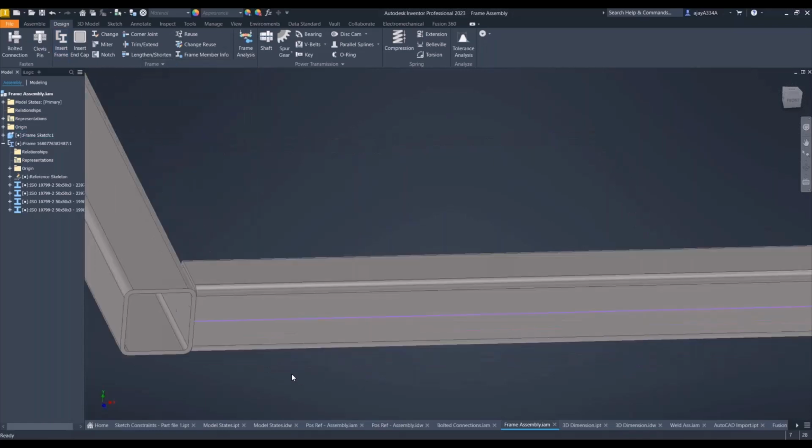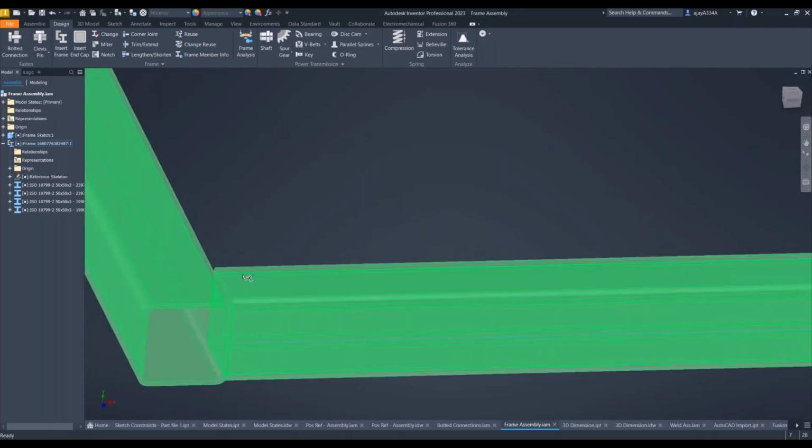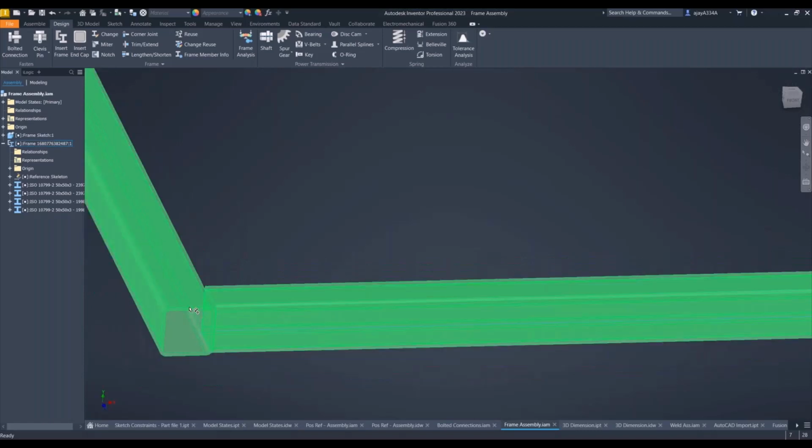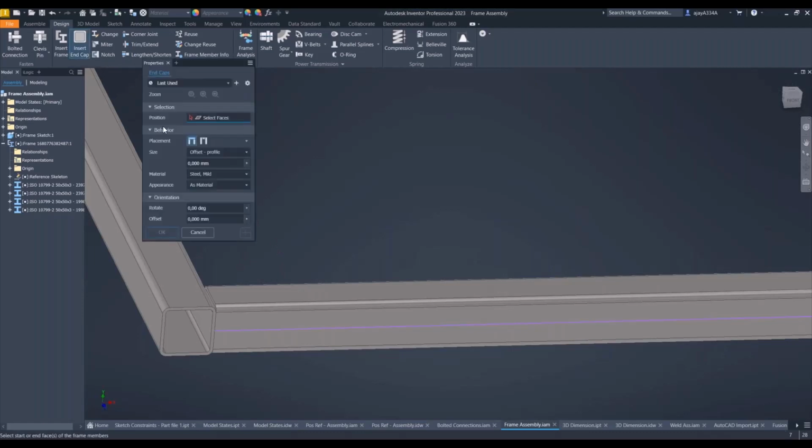Odd little frame, but when you've got a frame that's actually set up like this, most of the time when the frame is cut, you've got a sharp edge. Now, do you really want to go and fill it or create all of that? What we'll do instead is to create an end cap. And you've got 2 types of end cap. So you can place it on the outside, or you can place it on the internal position. So I'll show you both quickly.